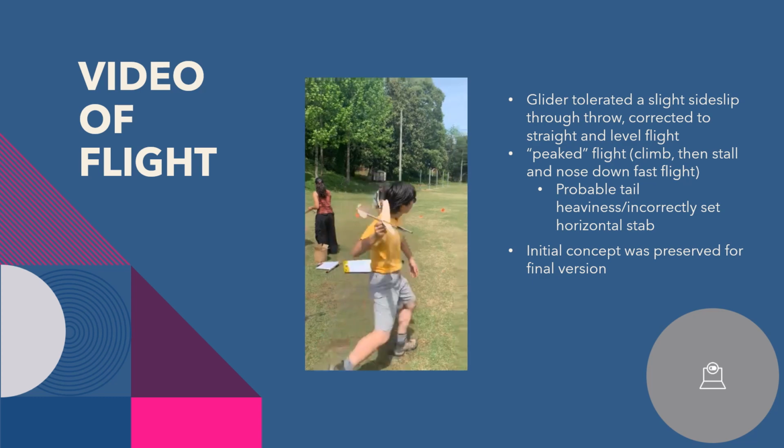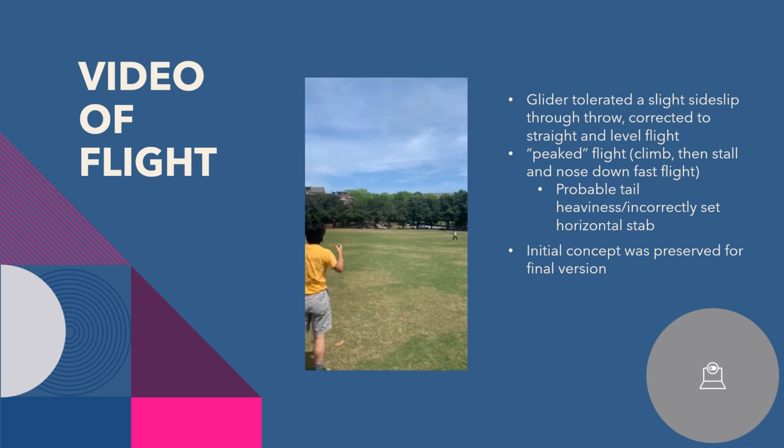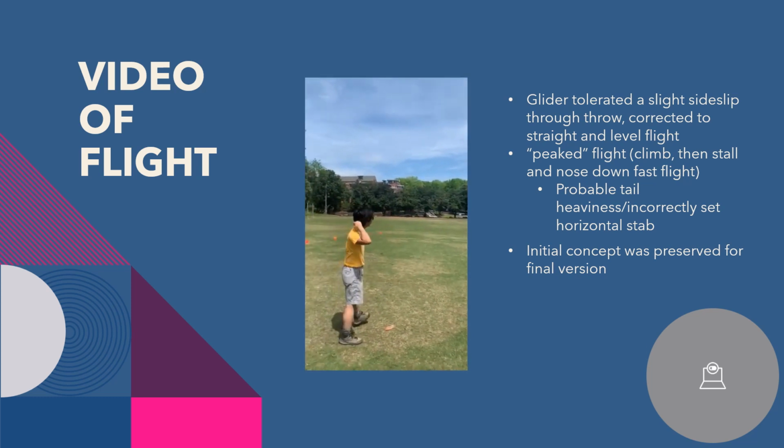So here's a video. It took only a few seconds. However, the glider flew in this peaked shape, reaching an overall distance of about 60 feet. It tolerated a slight side slip, which proved the correctability of the large dihedral. This flight profile is likely a result of tail heaviness or an incorrectly set horizontal stabilizer, which resulted in a stall. As you can see, the initial concept is mostly preserved for the final version.